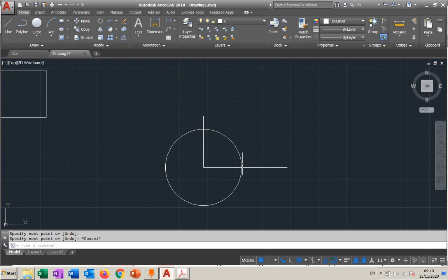So far we explained that for deleting, you can select the object and delete it, but how would you be able to delete a portion of this one or this excess part? Those all we call modification. You have a drawing and you modify it. I'm just going to show it to you. For example, I can simply use trimming for the excess part I wanted to delete.